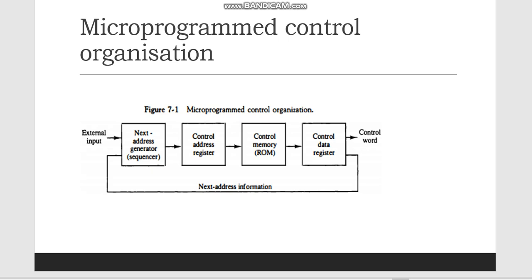Two methods of implementing the control unit are hardwired control and microprogrammed control. The design of hardwired control involves the use of fixed instructions, fixed logic blocks of arrays, encoders, decoders, etc. The key characteristics of hardwired control logic are high-speed operation, expensive, relatively complex, and no flexibility of adding new instructions. For example, CPUs with hardwired logic control are Intel 8085, Motorola 6802, Zilog 80, and any RISC (reduced instruction set computer) CPUs.